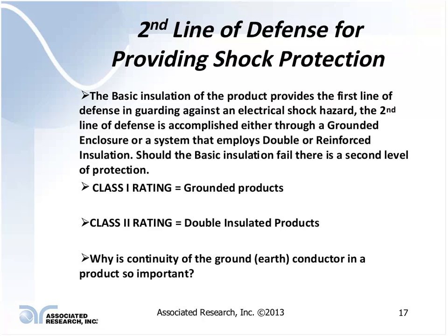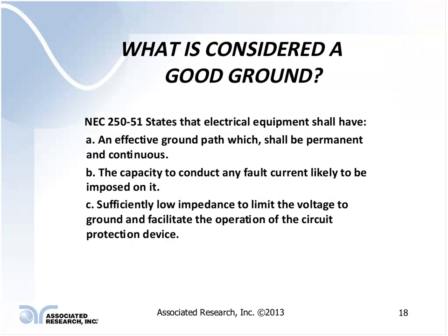Okay. If it's a Class 2 product, then basically your test potential is normally 2 times the AC potential that is used for basic insulation alone within the product itself. So, if you're doing a 1500 volt test for basic insulation, then the double insulation would be tested for the most part at usually around a 3000 volt level. Okay. What is a good indication of a good ground?